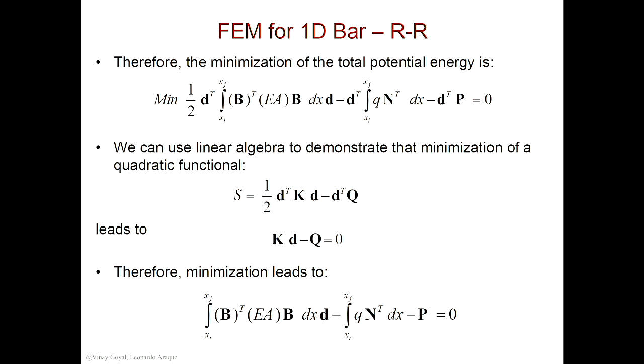What does it mean for the second D to be on the outside of the integral? So the question on the table is, what does the D outside of the integral do? Not the D transpose, but the D on the right side of the dx. This D represents the unknown coefficients, ui, uj, uk, and this D here is ui, uj, uk, but transposed. So you can pull it out, because it doesn't depend on x. The answer is because these are unknown coefficients. They don't have an x. They don't depend on x. Okay?